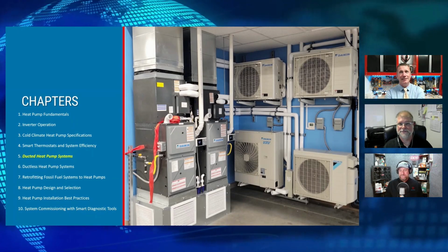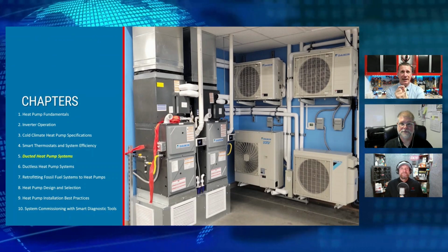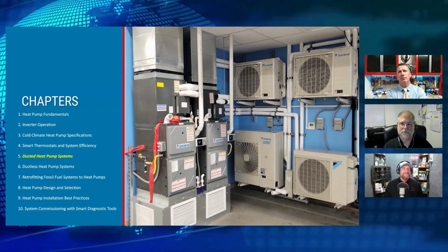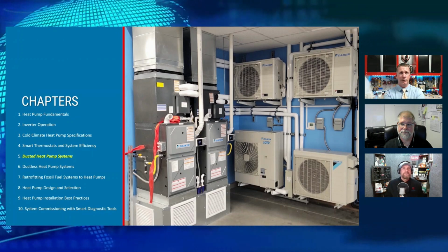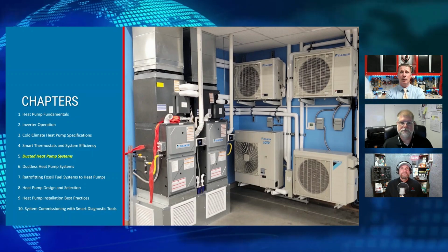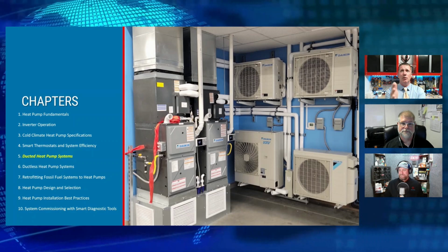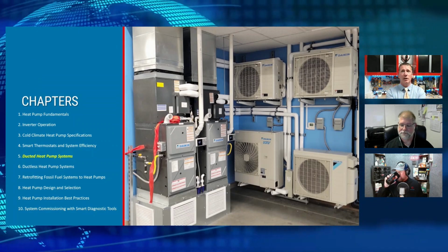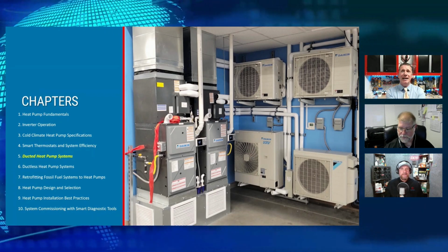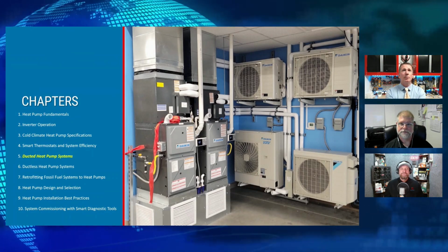So as we start getting into some of these more advanced pieces of machinery, it is so critical, especially when we talk about things like airflow, right? So here's an example of some equipment. This was one of the facilities that we've visited here recently. When we start talking about inverter installations and the changes of motors, if you haven't realized, we've already moved away from PSC motors into ECM motors for the majority of our indoor units, right? So we've replaced them with higher efficiency motors. I cannot get the performance out of an inverter, particularly if I have not started with proper airflow.